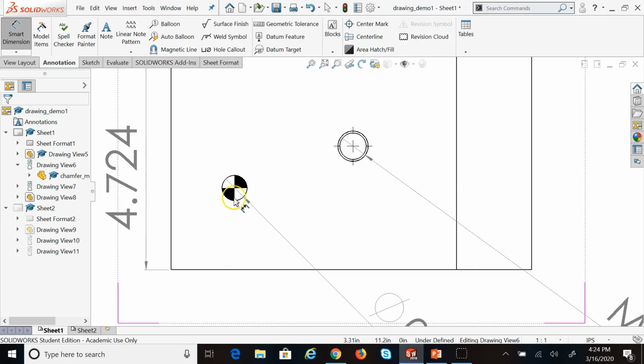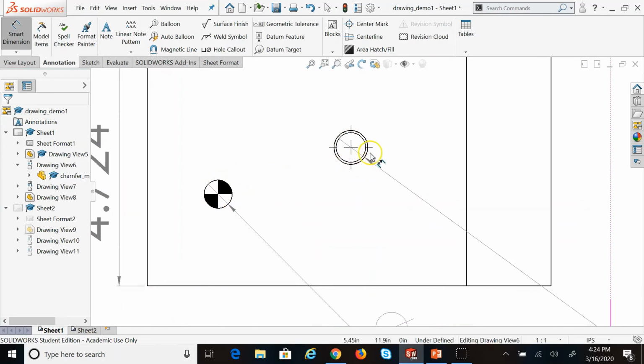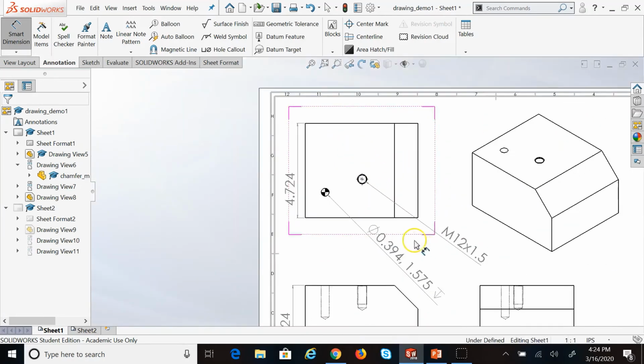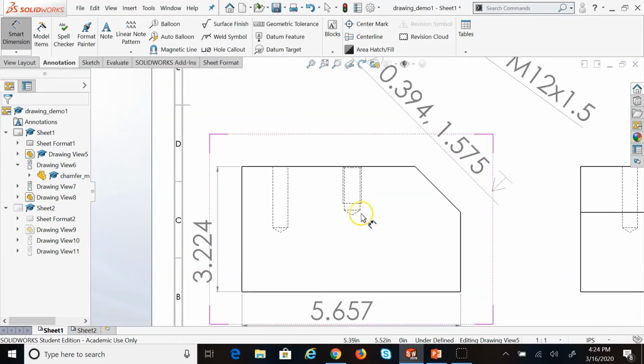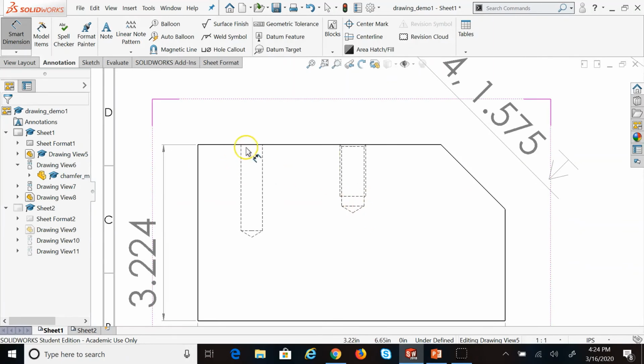One is that a simple drilled hole without any thread is just a simple circle, but the threaded hole has two circles if you look from the top. But better than that, when you look from the side, that's where you can tell. This one here is a simple hole, but this one has an outer rectangle, which is the thread.